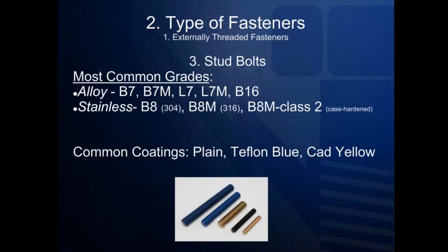However, the most common stud bolt for flanging together pipe is ASTM A193 Grade B7, which of course you will always mate with an A194 Grade 2H heavy hex nut. To make B7M studs, you'll actually start with a grade B7 material and then reheat treat it, thus the M stands for modify. B8 and B8M is actually completely different in that B8 is a 304 type stainless steel equivalent and B8M is a 316 stainless steel equivalent.